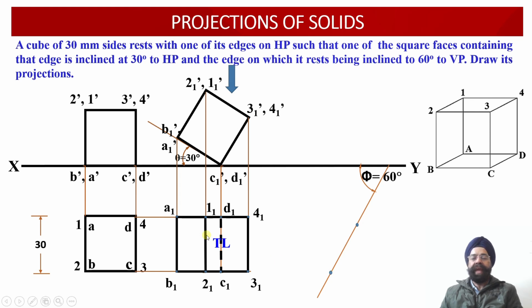So how can we have the rectilinear transformation of this plan projection view at an angle of 60 degrees? So please check. We know the distance between C1 and D1. So this distance is already available with us and it is true length. And since this C1, D1 distance is true length, angle phi has been marked over here equal to 60 degrees.